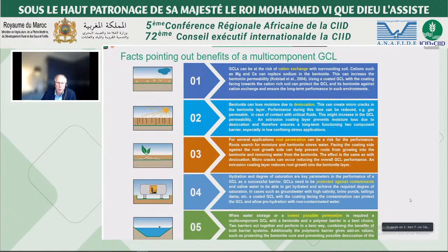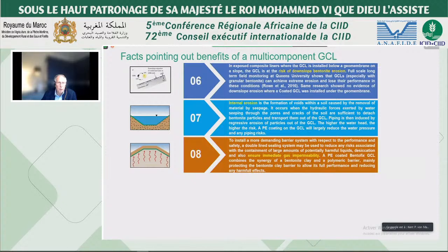I won't go too detailed in the advantages or why we're using this. I'm just showing you that you can protect the clay core, you can prevent the bentonite from desiccation, you can prevent root penetration into the material, you can give it a chemical resistance, you can improve the permeability of the system, you can also prevent downslope erosion. That's another topic which might not be that relevant in this application.